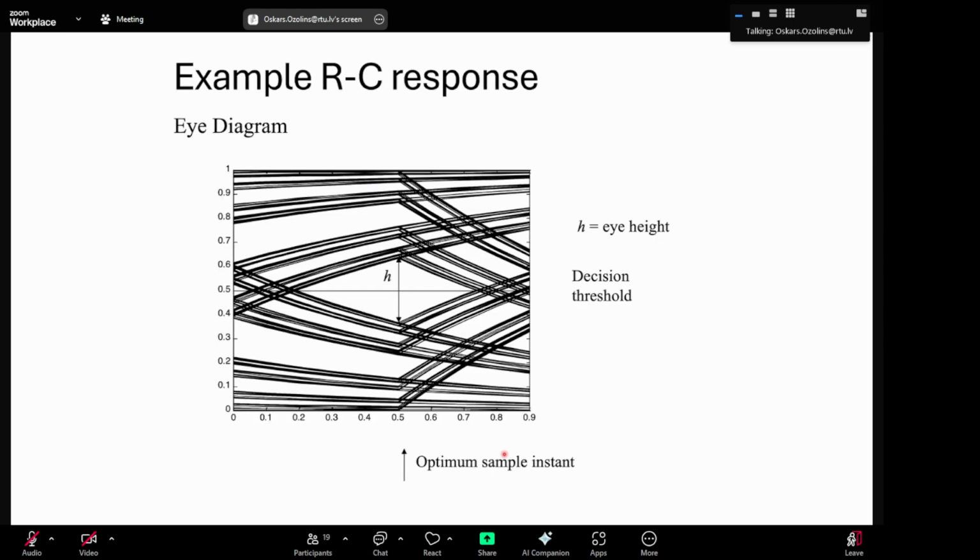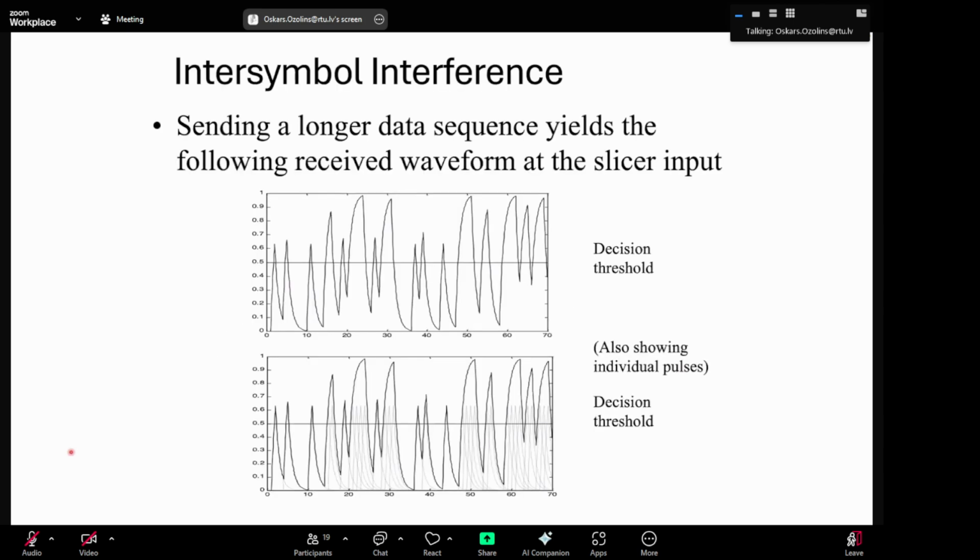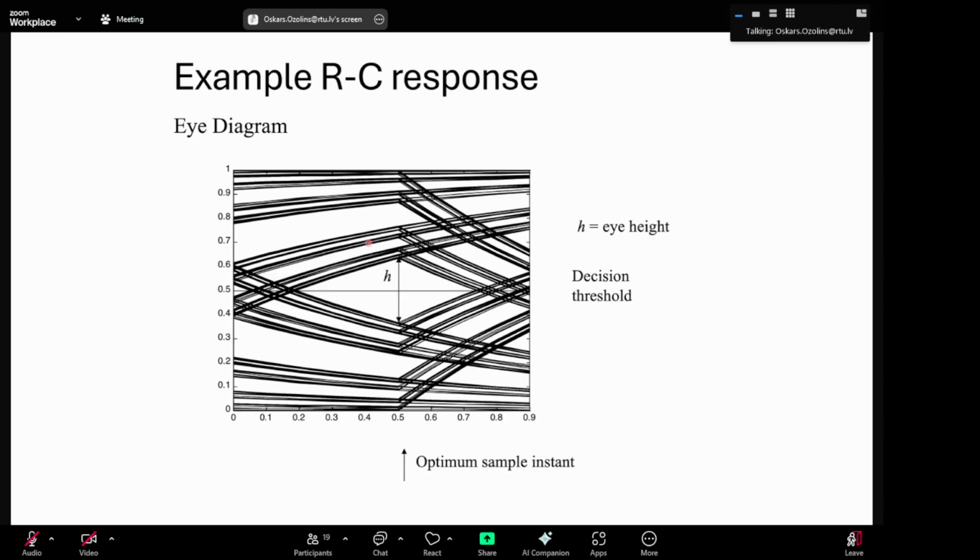So here is a typical eye diagram where you overlay all these pulses, and I think this one is important. Depending on the pattern you have here, depending on whether you have several ones and several zeros, or several ones and just a few zeros, you will have a double trace, depending on your bit sequence, say the random bit sequence, for example PRBS7 here.